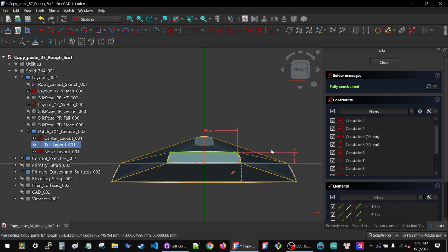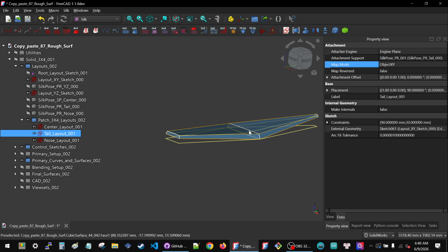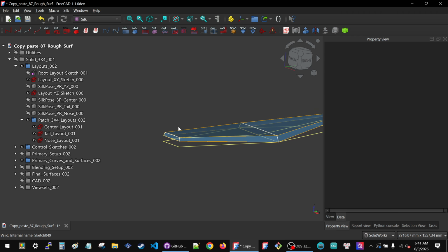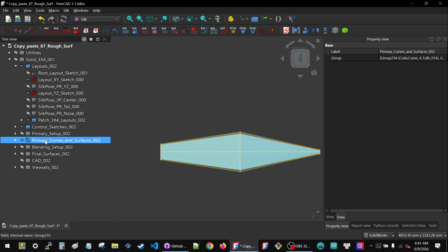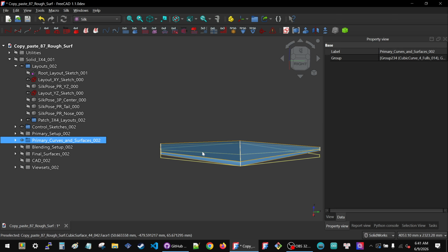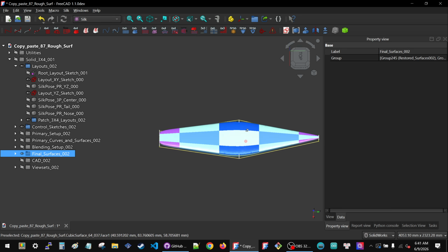Right. See, the way this works from a parameter standpoint is that this dimension controls the height of the rail, which is also the thickness of the board in this area. And then this dimension controls the transition from deck to rail. But I still have curves on every single one of these edges to really tweak things. But this is the basic idea. And here we're looking at, we haven't shaped any of these curves, but even with unshaped curves, we already have all our blends in place.